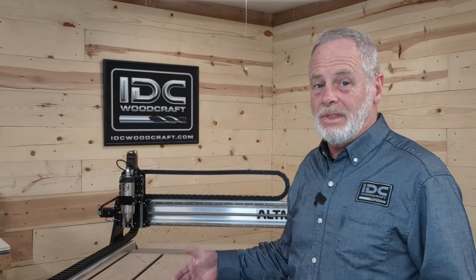So what I did is, I've got the Altmill 4x4, but they've got the 2x4, and there's some people working metric. So I did designs for the Altmill 4x4 and the 2x4, in inch and metric. The inch version, all the grid lines are 4 inches apart, and the metric version, all the grid lines are 100 millimeters apart. And then I created G code for every single one of those, and I verified them on my Altmill just to make sure that they all work.